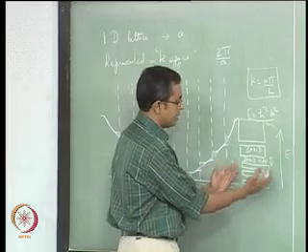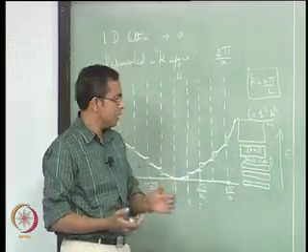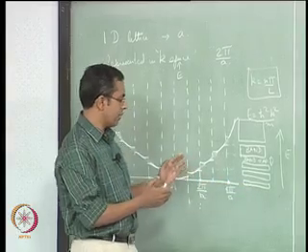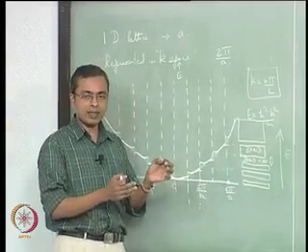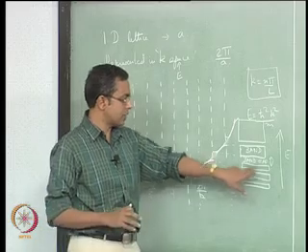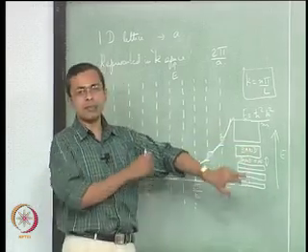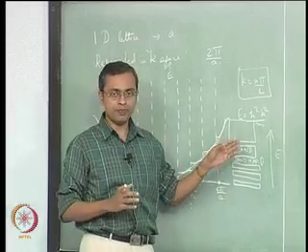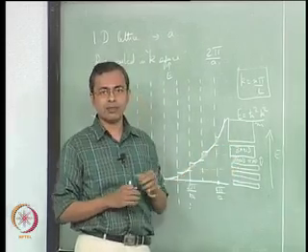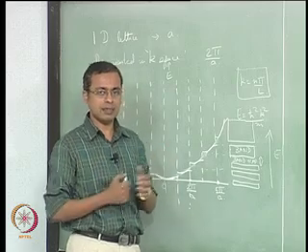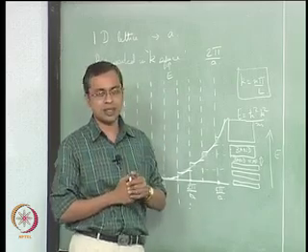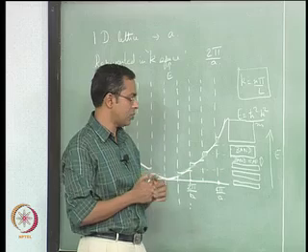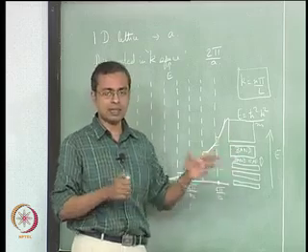This kind of a representation, by the way, is called a flat band diagram, because a lot of the detail of the actual allowed k vectors and such are not actually shown in this kind of a diagram, but this is the kind of diagram that is typically shown to us in high school physics, because it is much easier to follow. And in fact, for certain types of activities where we are looking at transitions and energy levels, corresponding energy values associated and so on, this kind of a representation is adequate.